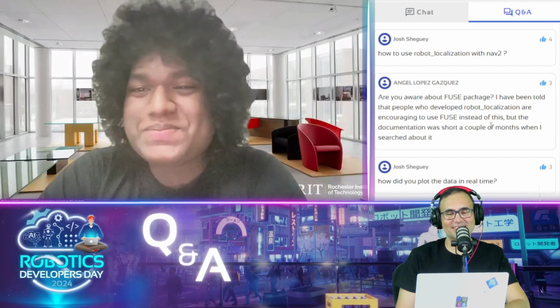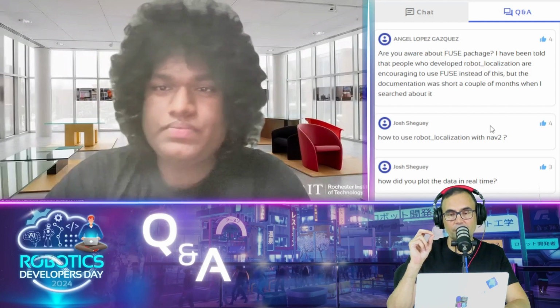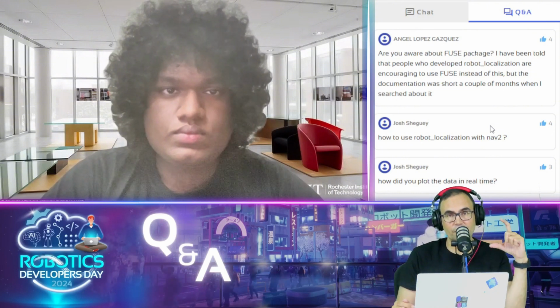Okay, yes, thank you. Let me suggest a couple of ways. One could be, for example, just feeding the odometry that you are getting into AMCL, because the odometry you have filtered, which combines wheel odometry and IMU, is a better odometry.